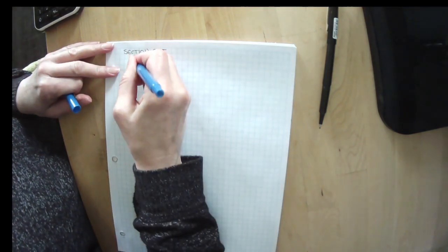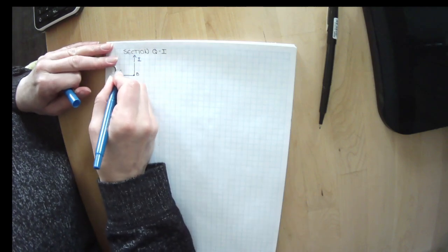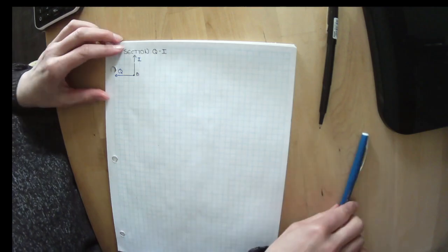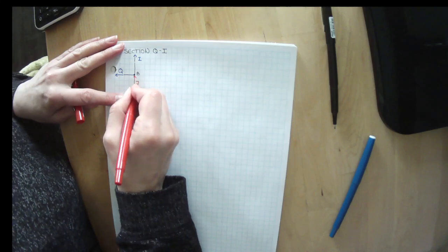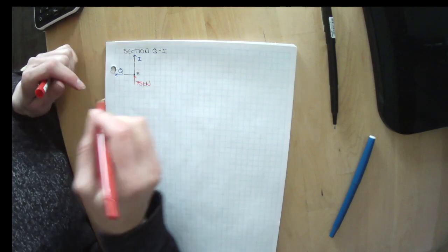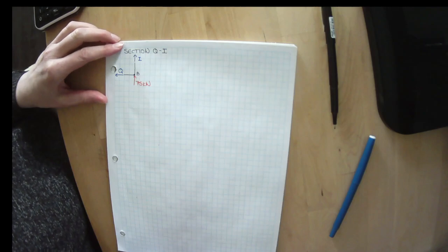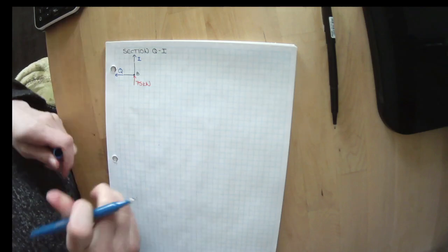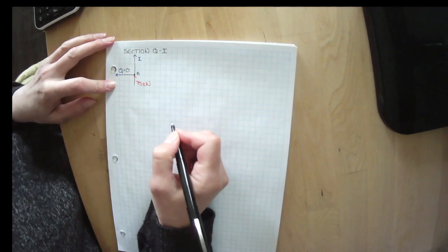We've got our I and our Q both drawn in the tensile direction. We know that at node 8 there is also a 75 kilonewton reaction happening there. We have already solved previously for Q. We know that Q equals 0.